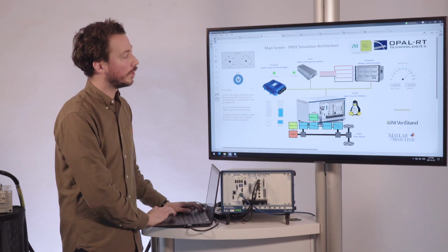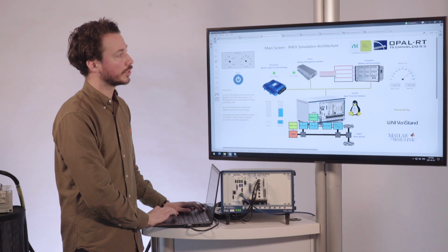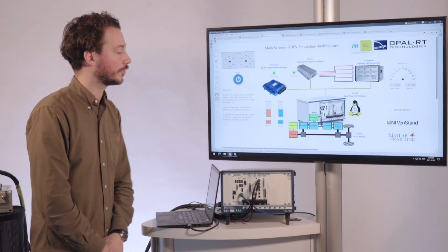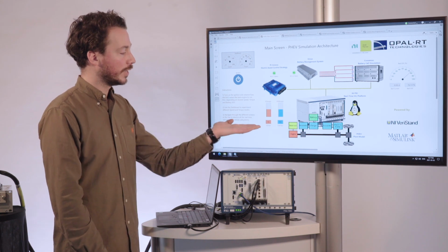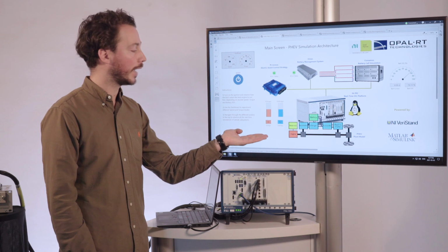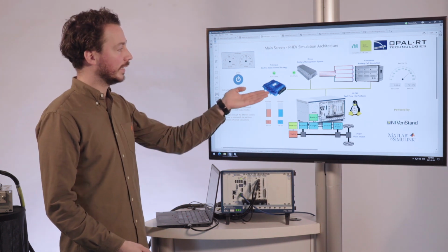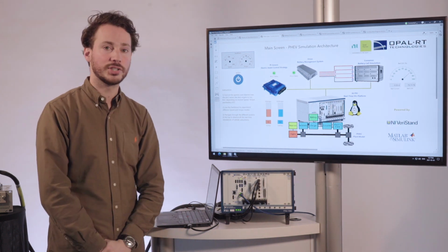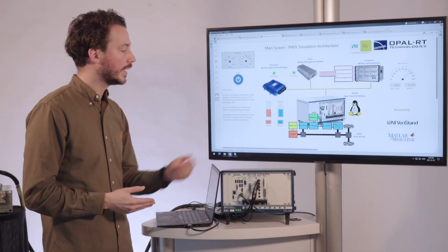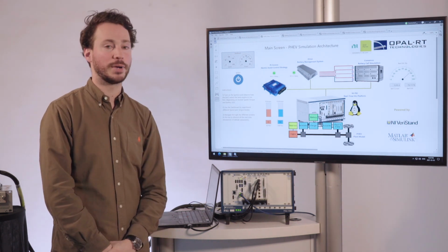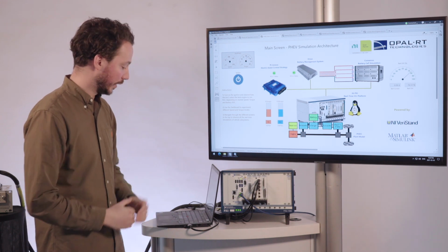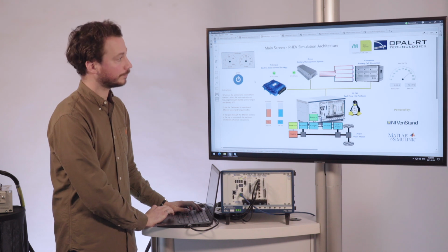So like I mentioned before, if I go, for example, to a torque that's a little bit too much for the electric machine to handle at a certain speed, we can see here that now not just the electric machine is running, but as well as the combustion engine. Okay? So in certain situations, the EACS, the electric assist control strategy, has determined that there is simply too much torque for the electric machine, and then we can have the combustion engine turn on and help out. And that's how we can have the parallel simulation.